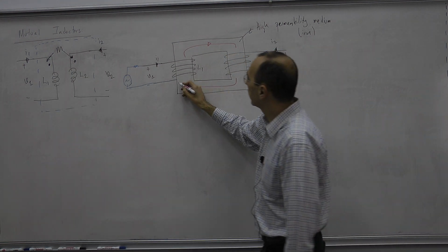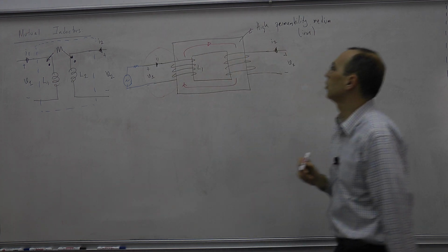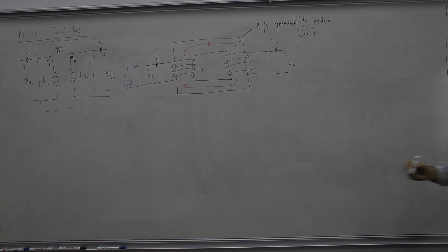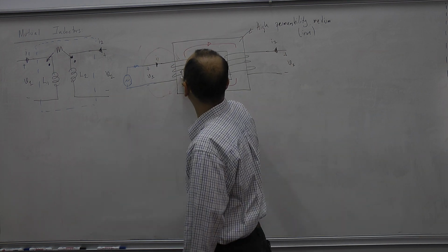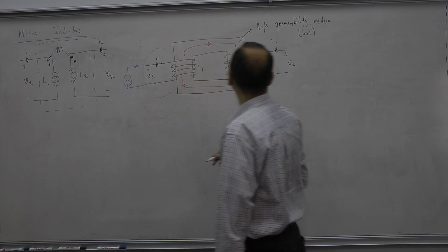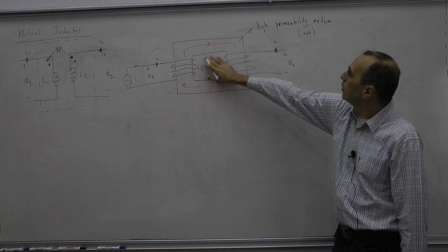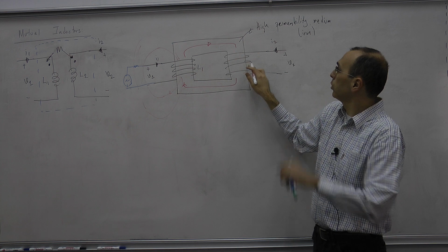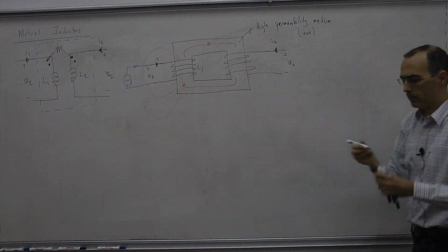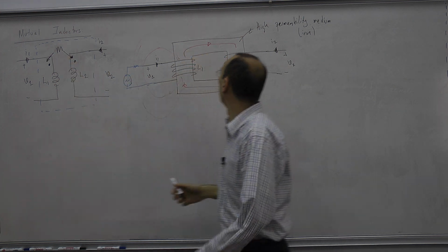Of course, there can be leakage magnetic field and so on across over there. Leakage, that you may think about. What is interesting is that if I have an energized coil number one, some part of this flux, or some part of this magnetic field, is also intercepted by the second coil. That will be related with this mutual inductance value M.